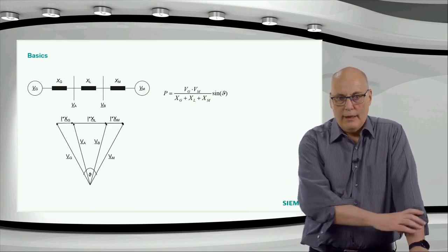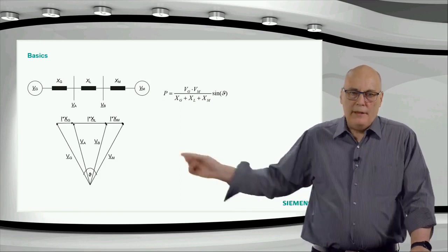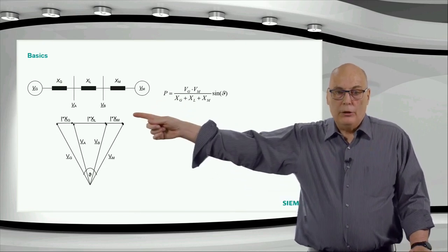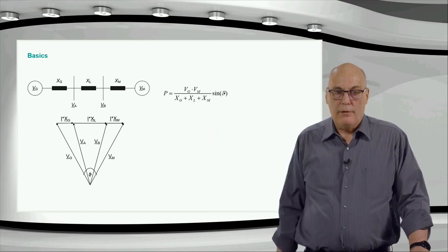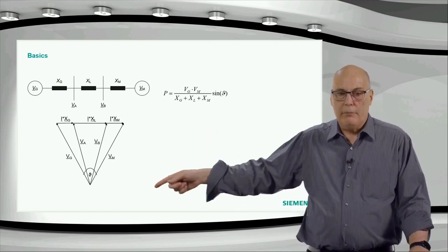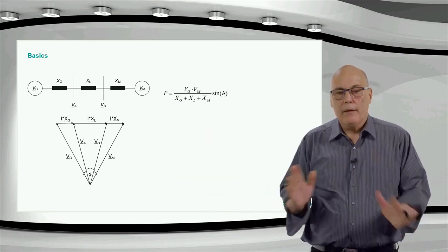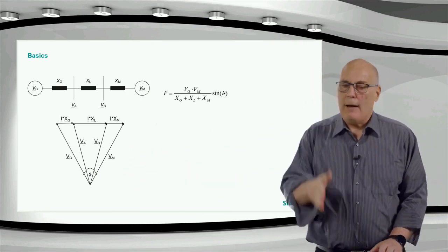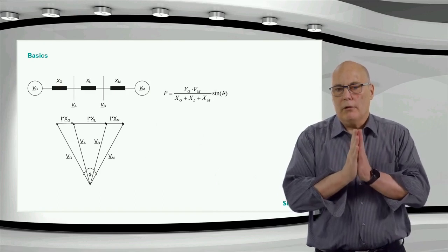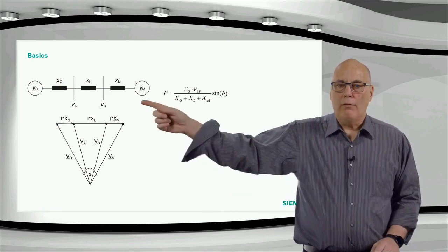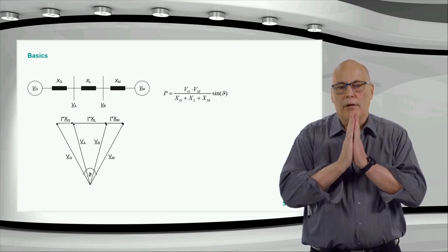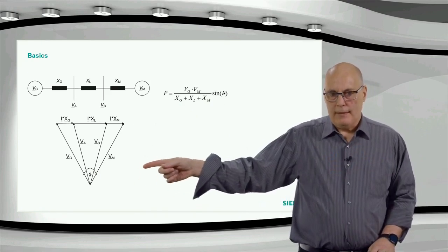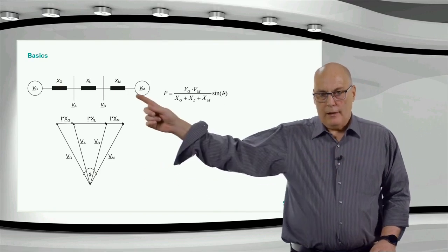That's shown in this diagram over here. What is missing in the diagram is obviously the load current, but that is shown at the top here. You can see the load drops, the three load drops. The load current would effectively be exactly at the bisection angle, vertical at the bottom from the source upwards. That's the load current. Remember, for active power, for P, we get real power only if the current is in phase with the voltage. So in this case, it would be exactly in the middle. And the current would flow left to right.